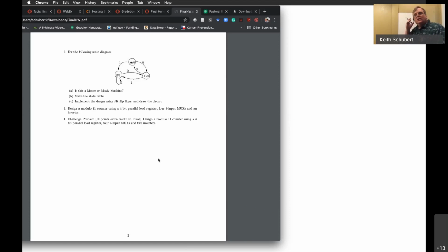So is the output the current output and not the next state output for question one? Outputs are always where you're at, because the next state hasn't happened yet. Technically, when you get to the next state, it's then the current state. So when we're doing outputs, we always deal with my current state and my current input. Next state is telling you where you're going to go in the future, but you don't need to handle the outputs. You'll figure out the outputs when you get there. So you're always working with the current state and current input.